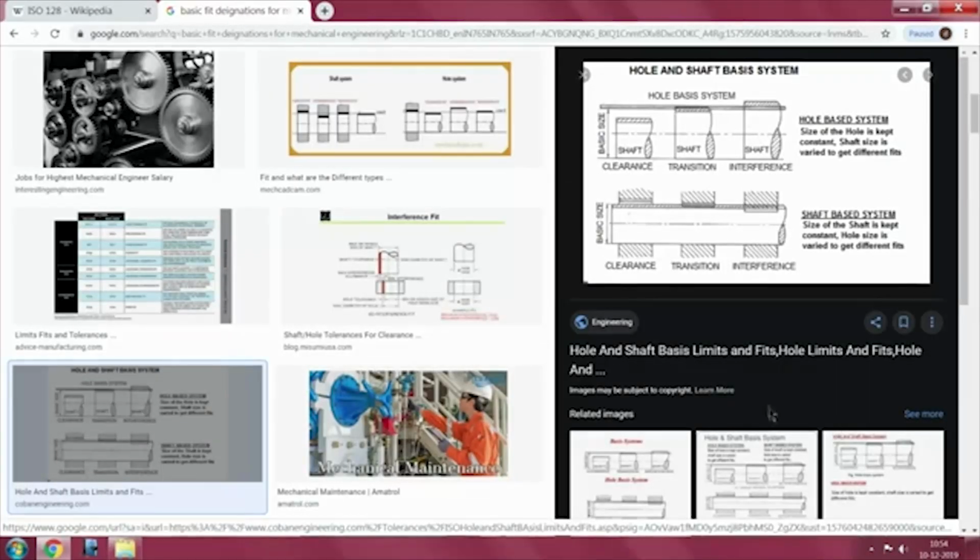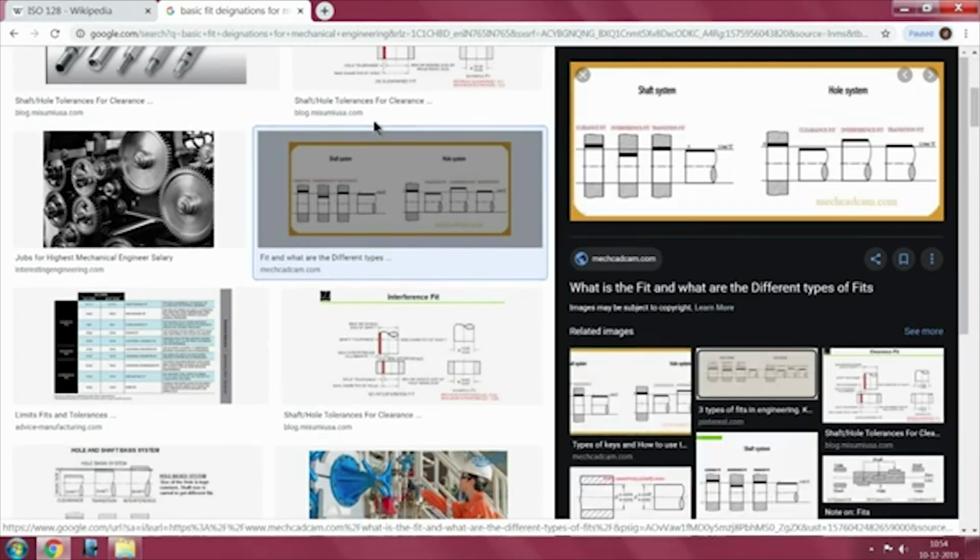When you push them together, there is in fact in ISO, which I will come back to some other time, a list of types of fit that are possible, all standardized, whether you call it the JS system or some H system and so on. All these have been standardized, and mechanical engineers' reference books will give you what you need to do.